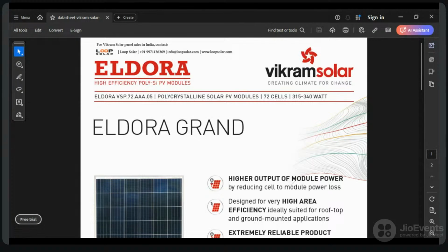The assumption is only for the calculation, not for the designing purpose. For designing purposes, it is okay if you have the battery backup time, but in general, for research purposes, we cannot assume, because inverter efficiency will vary and it won't be ideal. I took it for the calculation requirement because I need to know the backup time. Inverter efficiency varies by manufacturer, and if you design for research purposes, you will get the maximum inverter efficiency, because in research we need to go for the maximum. Only for designing the backup time I took it.